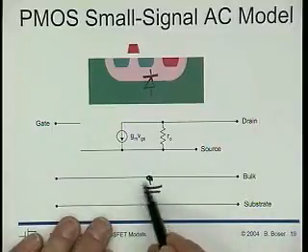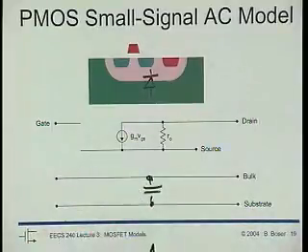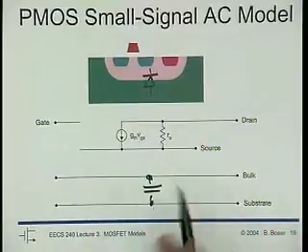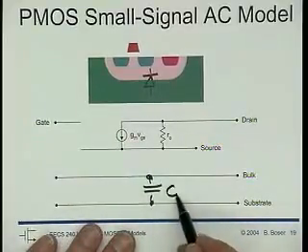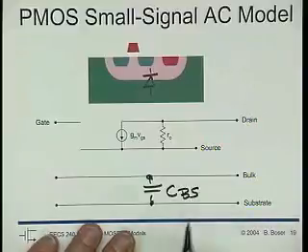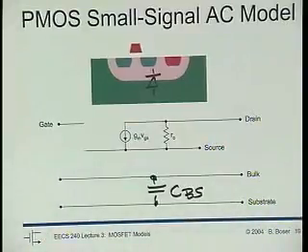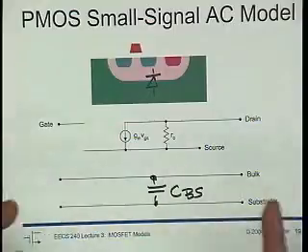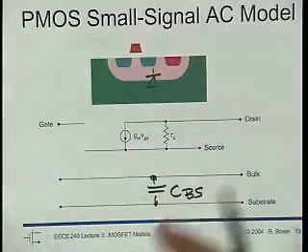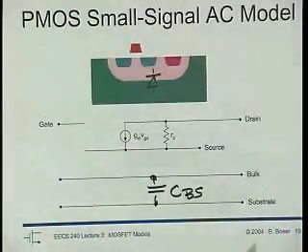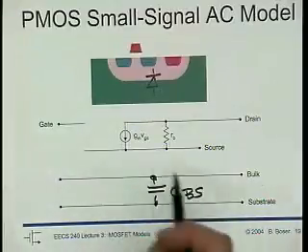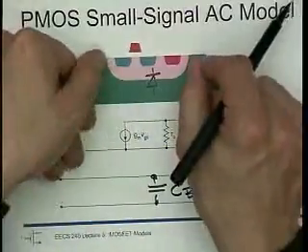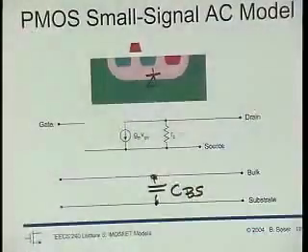And the rest is the same as before, but there is this additional capacitor C bulk substrate, and if it matters in your circuit, and sometimes it matters, cuts down the common mode rejection at higher frequency of diff amps and stuff like that, then you need to specifically stick it in. You need to figure out how big this thing is and hack it into SPICE.